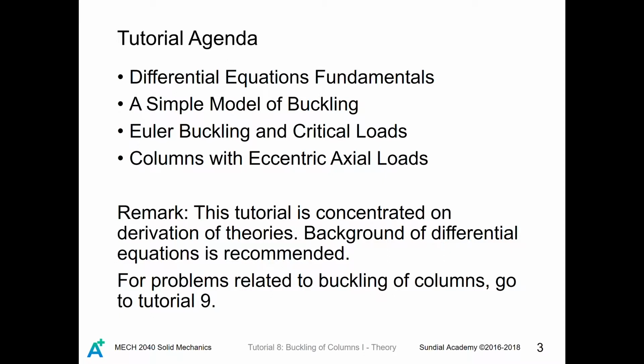I will show you some of the techniques of solving differential equations, as well as show you how to solve the buckling equations in the Euler continuous model by using differential equations. There are 4 models in total, representing 4 support conditions, but I will only describe 1 or 2 which are particularly difficult.